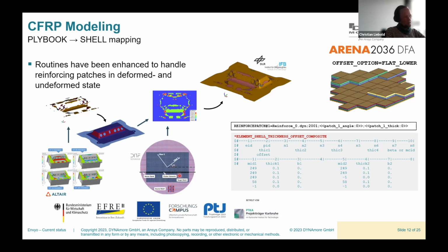These weaving simulations have been performed with beam elements, and they had the inclusion of a sensor band, which is used during the manufacturing process to measure effects of temperature or accelerations and such, and should be used to first evaluate the manufacturing process of the part, as well as the life cycle of the part.